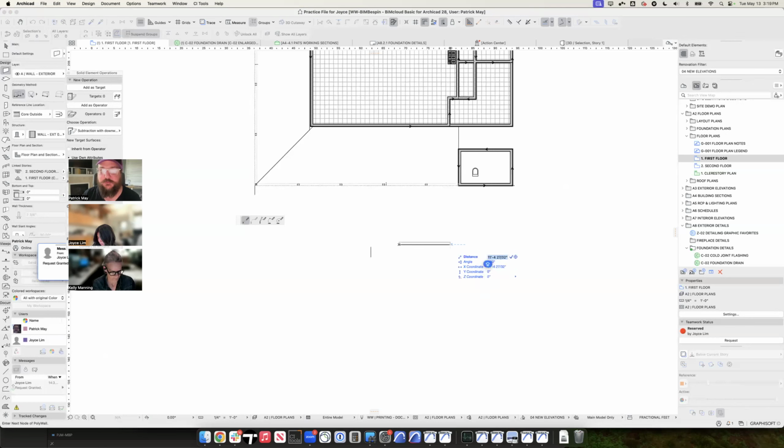You can also tab through this. So if I did want it to be at a 10-degree angle, I can type 10 degrees. Or I can type X and Y coordinates. So I can say it's over 12 feet, up 20 feet, and define the coordinates for that endpoint. How are you toggling between all those things? Just hitting tab. Or the direct shortcuts are R for radial distance, A for angle, X for X coordinate, Y for Y coordinate.